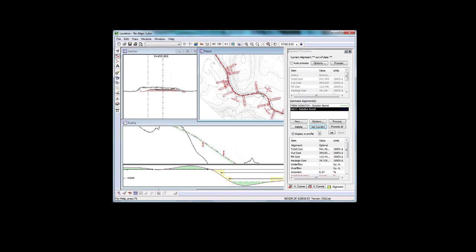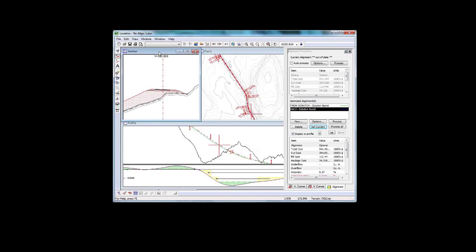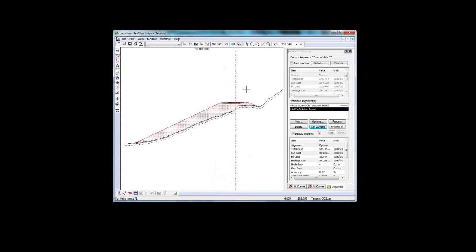This cross section near, I think, where was it that I was looking that looked interesting? I'm just going to look for an area where I've got large, here we are. Look at this. This cross section here has big fill. That's got to be expensive. And it could be moved horizontally here to produce a small amount of cut and a small amount of fill. Maybe that's a better way to go. So this is near station 1180.